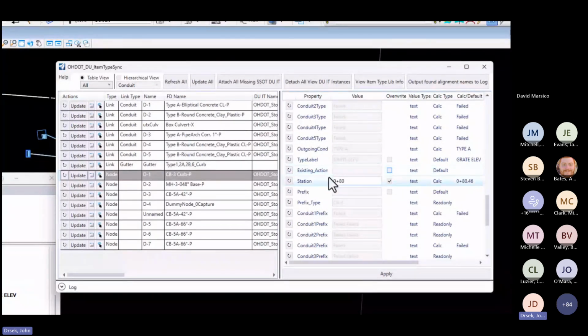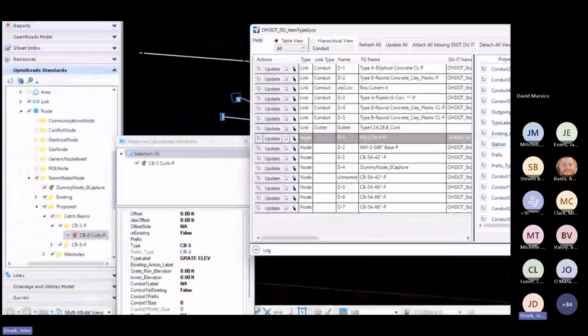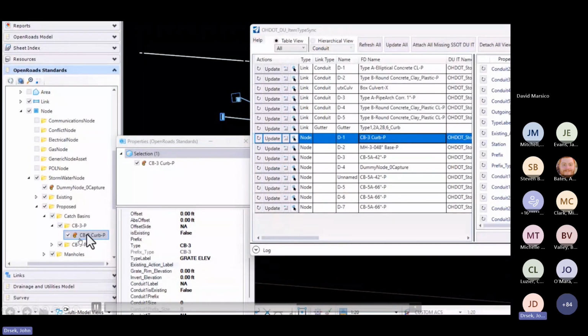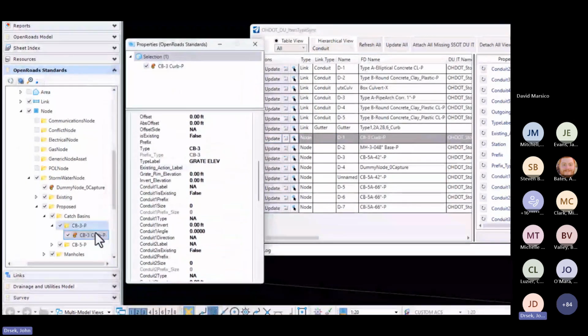So you could go over to your feature definitions, and maybe you copy one and rename it to something like to be removed, and then you can get all your to be removed nodes on the same feature definition. If I go over to my Explorer and find that feature definition and look at the properties on it, this is where all the defaults are set.